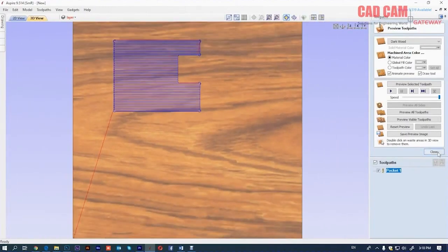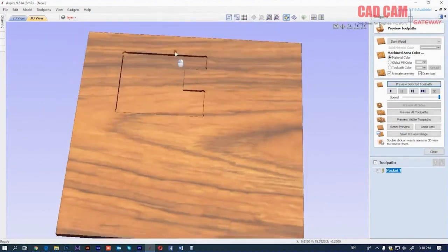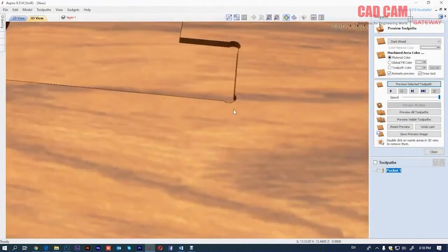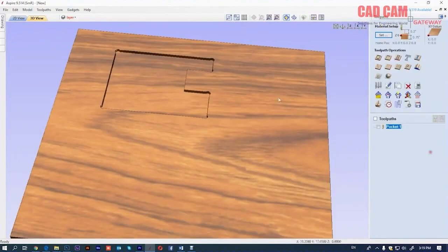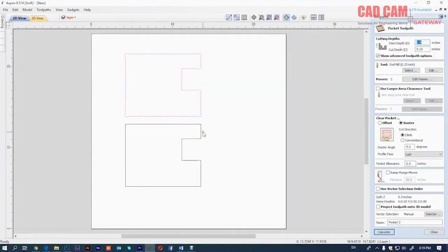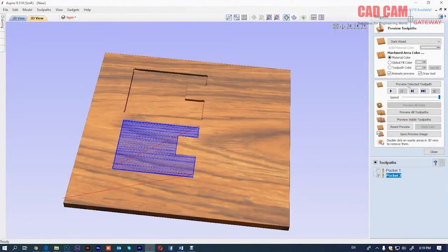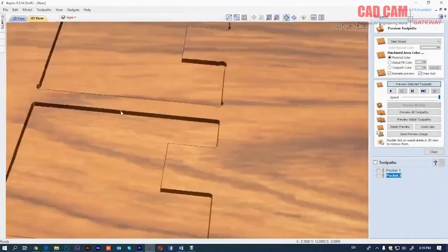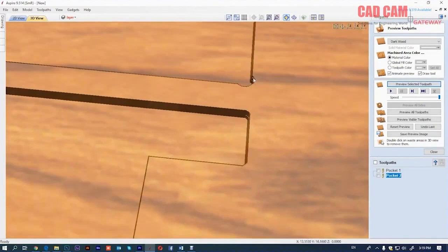In the same way, you can preview how, when it was cut, its corners were made a bit deeper. Now coming back here, I'll take another job like this one with the same specifications to cut it as well. Now you can see the difference in front of you. These corners have moved outward, and this corner has become rounded at the same spot, because the radius of the tool's diameter will be applied here.